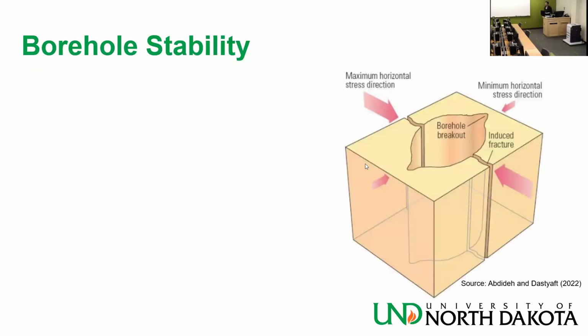Borehole stability, which you should have already seen in geomechanics, is very similar. We talked about tension and we talked about compression, shear compression. Two types of failures. Mode 1 is tension, hydraulic fractures, etc. Mode 2 and mode 3 are compression, shear failures.